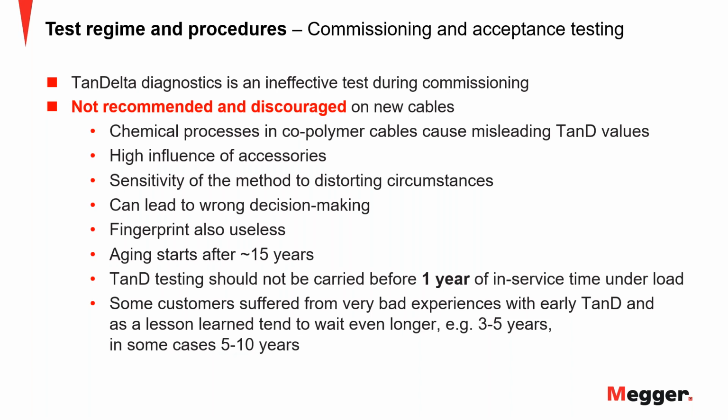initial disaster. And a lot of customers that we see, they don't really care a lot about tan delta testing, especially if your asset manager is quite technical and he understands cable, he knows about this. I mean, this has been published many times. This is nothing new, that copolymer cable shows this behavior, and that a tan delta test on new copolymer cable is very questionable or ineffective.